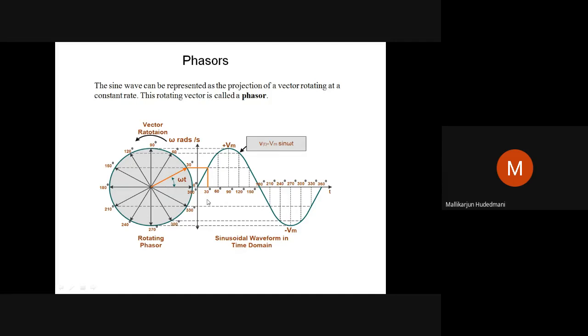Retrogressive waves are represented by a clockwise rotating vector. So all our standards are concerned with progressive waves. Therefore, whenever we say waves connected to electrical systems, definitely they are progressive waves, for simplicity of understanding. So the vector must rotate in the anti-clockwise fashion. That is the default nature of the rotation of the vector, which is a phasor.